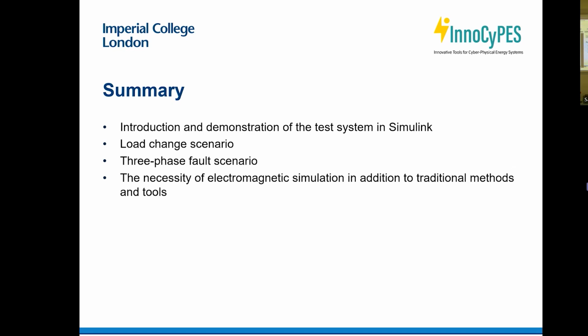In this talk, we saw that the Simulink file of the test system was introduced and demonstrated. We saw two scenarios, load change and three-phase fault, and the necessity of electromagnetic transient simulation, in addition to traditional methods and tools, has also been observed.